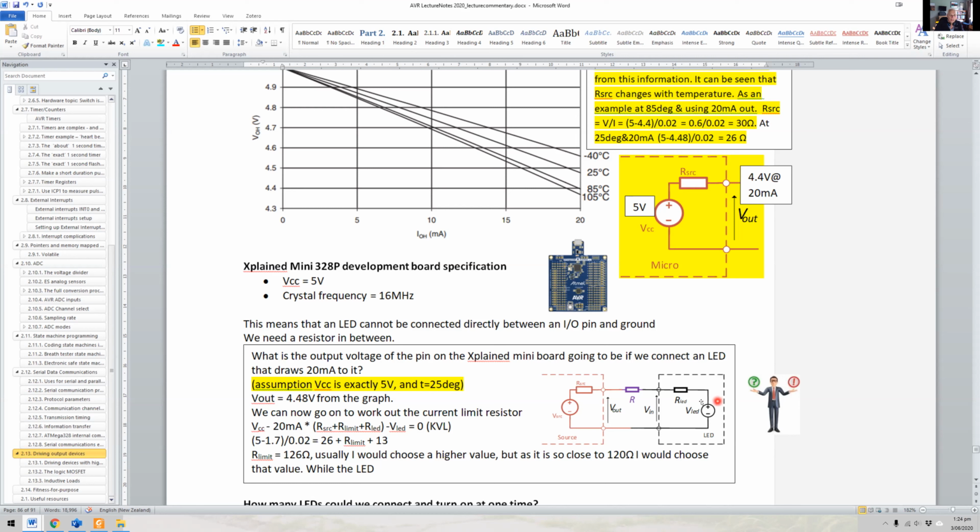And then, of course, I'm subtracting also this LED voltage here, and that will all sum up to 0. The reason I'm going plus, minus, minus is just the same sort of standard KVL that you would normally do. The direction of this voltage is this way, and the direction of this voltage is this way, opposite to the current, okay? So we've got voltage arrow this direction, this direction, and this direction. So it's this one positive, these two negative, and we end up with this understanding here, okay?